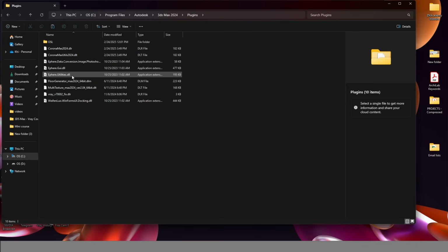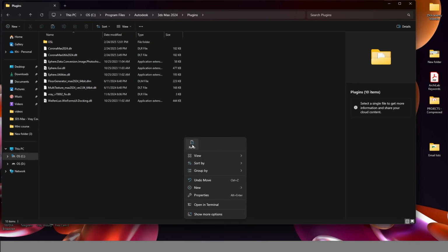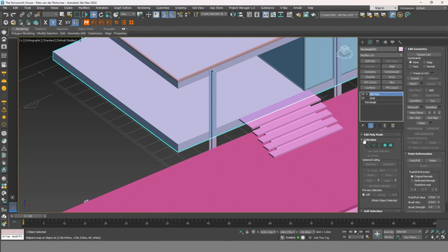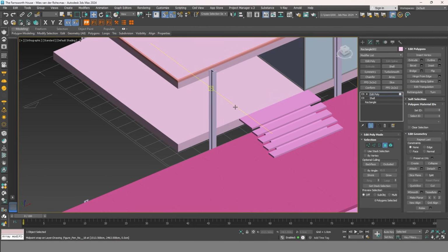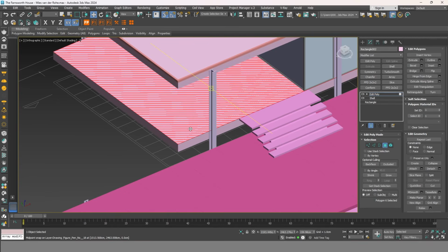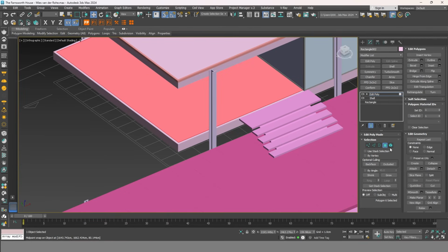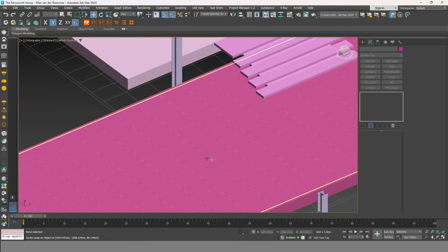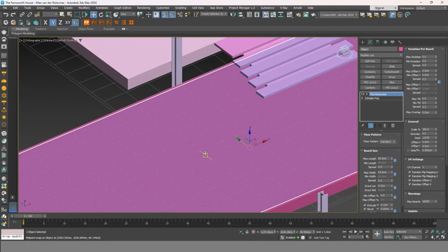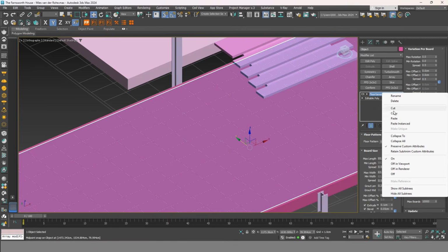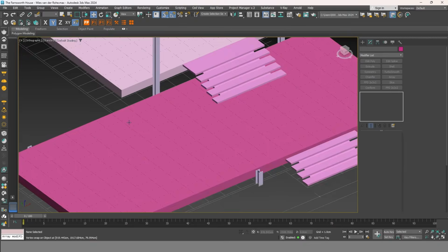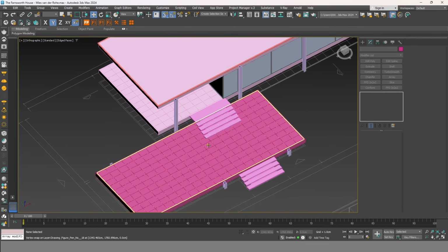Yes, this one. And then you need to paste it here. Okay, now let's add the other one. Let's create the other floor. So select the shape, go to polygon, again, inset it with 10 centimeters, detach it, and then this time you don't need to go over all the process again. You just need to come here, copy, and paste the modifier, and you will be done. You can press F4 to see the lines.